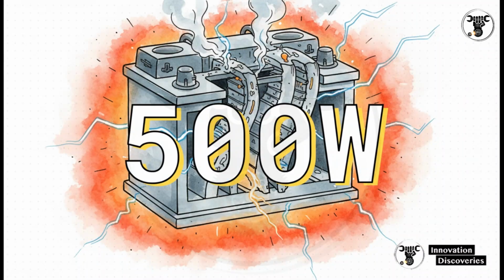Let's look at a genuinely shocking, real-world calculation. Imagine a standard 12-volt battery with just 0.05 ohms of internal resistance discharging at 100 amps. Super common for a starter motor, right? Well, that tiny bit of resistance creates a 5-volt drop. Your 12-volt battery is now instantly delivering only 7 volts to the system. Even worse, because power lost as heat equals current squared times resistance, you're instantly turning 500 watts of your electrical power directly into internal heat right inside the battery casing. In extreme cases, this is exactly what leads to warped plates, evaporated electrolyte, and thermal runaway.